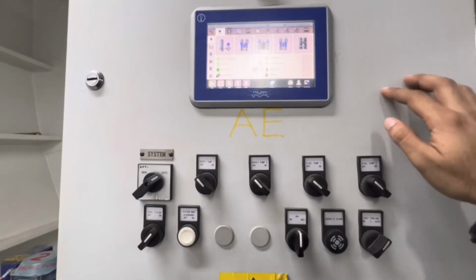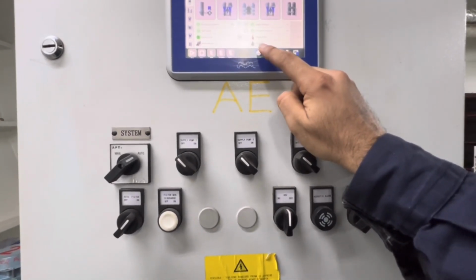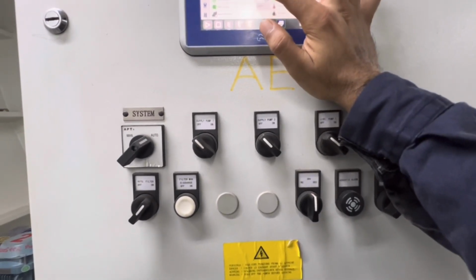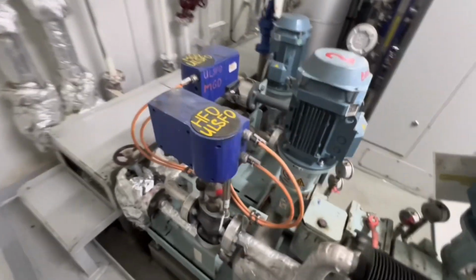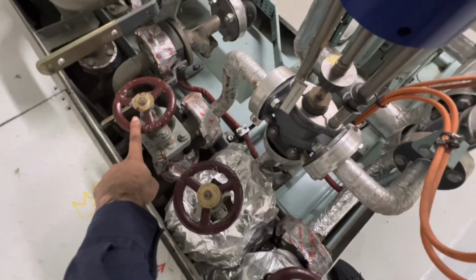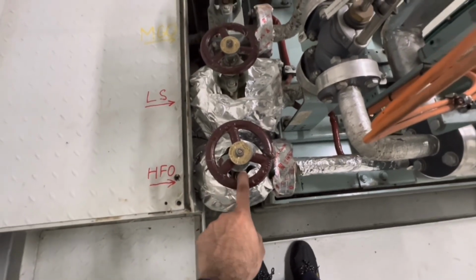Now I am near the auxiliary engine changing over panel. This is for the auxiliary engine. First of all, I will take over the control from the remote to local. So this is the changing over valve between heavy fuel oil and low sulfur oil. These are the three valves. This is coming from the MGO. This is from the low sulfur. This is for the high sulfur. So all the three valves we are keeping open all the time.